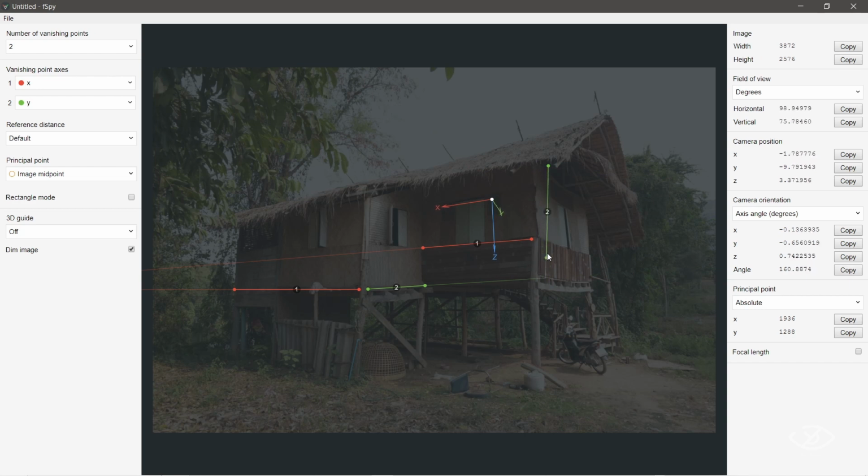Simply align those axes on the image. The best locations to choose are those having different depths. You may now use this cursor to check if the perspective of the picture is correctly aligned. I'll move the cursor to this location, which will serve as the origin point when we move this to Blender. Change x-axis into -x so that the z-axis will point upward.